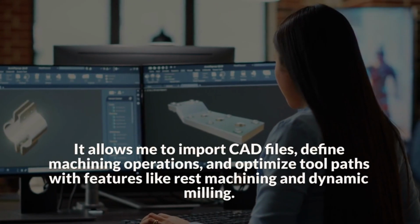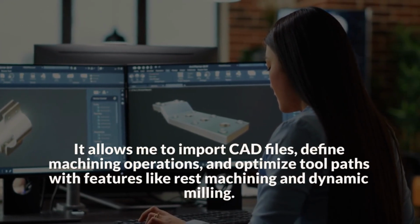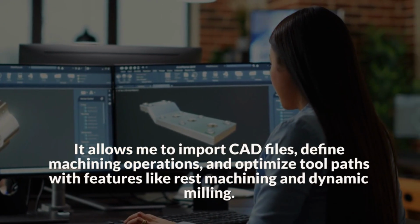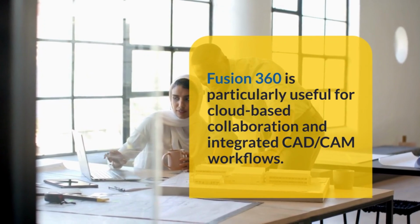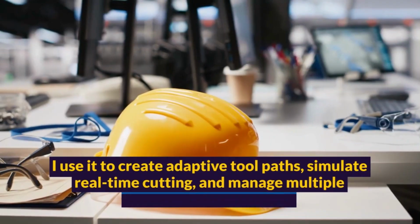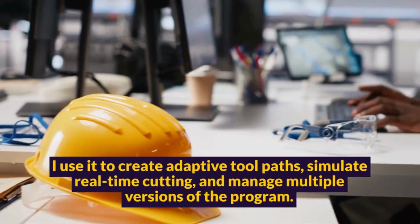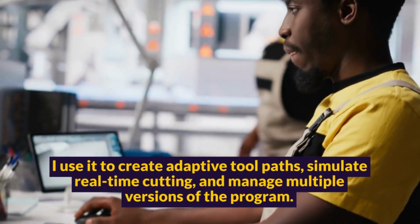It allows me to import CAD files, define machining operations, and optimize toolpaths with features like rest machining and dynamic milling. Fusion 360 is particularly useful for cloud-based collaboration and integrated CAD/CAM workflows. I use it to create adaptive toolpaths, simulate real-time cutting, and manage multiple versions of the program.